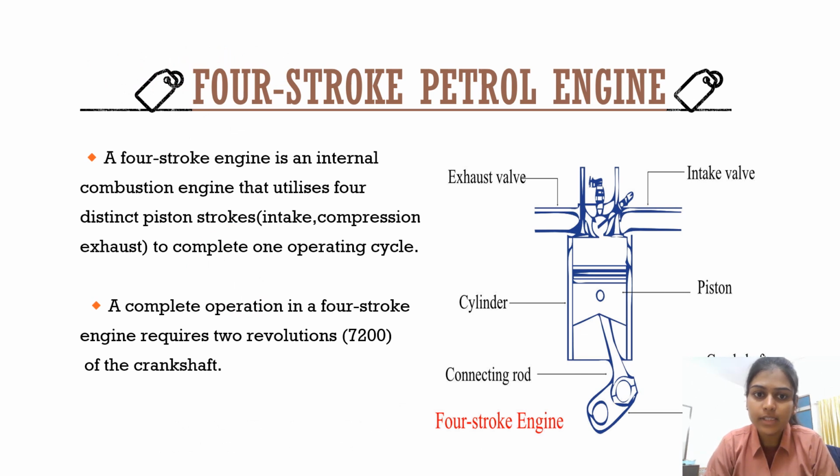First we will start with the introduction of 4-stroke petrol engine. A 4-stroke petrol engine is an internal combustion engine that utilizes 4 distinct piston strokes: intake, compression, power, and exhaust to complete one operating cycle. A complete operation in a 4-stroke engine requires 2 revolutions of the crankshaft.